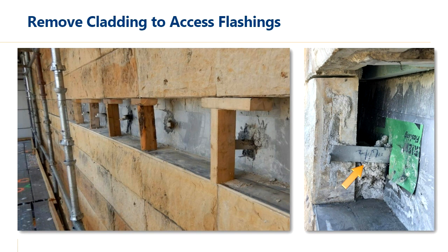On the right, we found a significant mortar droppings throughout all the shelf angles on this project. This was the main source of the staining that we were seeing on the outside. So this amount of 4 inches tall of mortar wasn't letting water get to the exterior as fast as it was designed to.